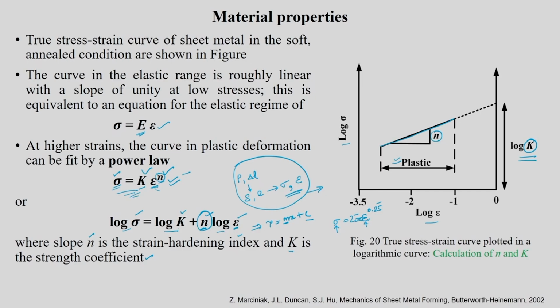So, now you will see that from a tensile test you are going to evaluate this type of equation, but in a tensile test the material is going to fail at one particular strain. Actual sheet forming operations may undergo large deformation, where strains can be much larger than the strain that you see in the tensile test.